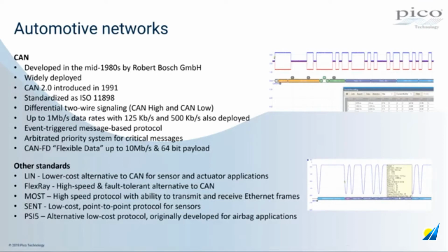So throttle position indicators, mass airflow sensors, temperature information that's being transferred typically to the engine control unit. And the majority of vehicles on the road these days are a mix of CAN and one or more of these other networks. So that mix of architectures has served the industry rather well for 10 or 20 years.